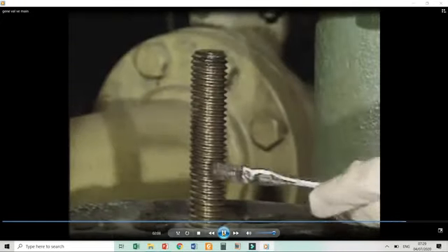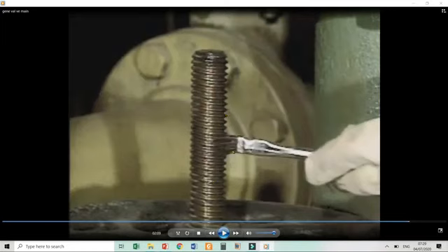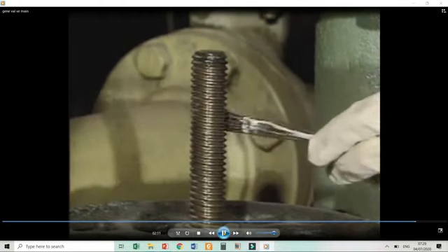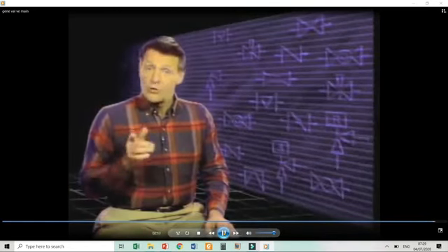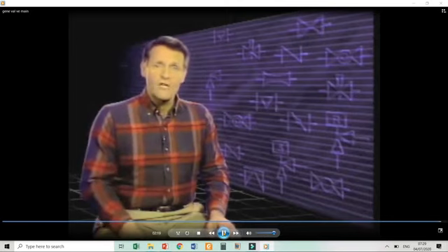For example, some valves have grease fittings and require the use of a grease gun to lubricate them, while other valves may have the lubricant applied directly to a component such as this valve stem. This person is cleaning the threads first, then applying the grease. Because there are so many different methods that may be used to apply lubricant, you should always check your company's procedures before lubricating a valve.